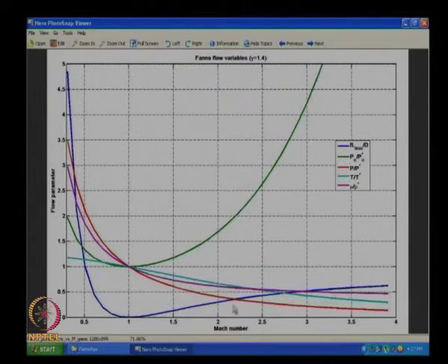When I go closer to M equal to 1, I find that going from Mach 2 to Mach 1, it needs only roughly 0.3 meters, if I assume the same f by D. While in this case, for the same f by D, it would have gone from roughly 0.65 or 0.7 to 1. Yes, that is what you are seeing here. It says that subsonic flow can handle a lot more length of the tube before it reaches Mach 1, while supersonic flow cannot. Important statement there.